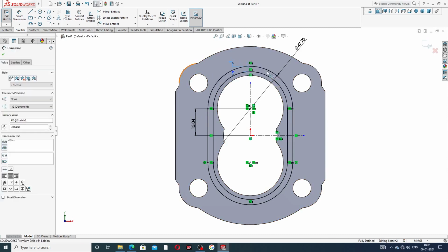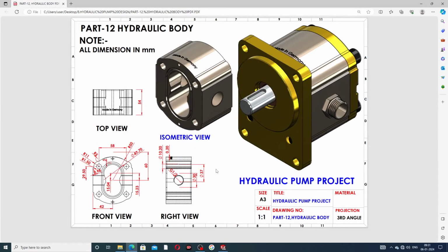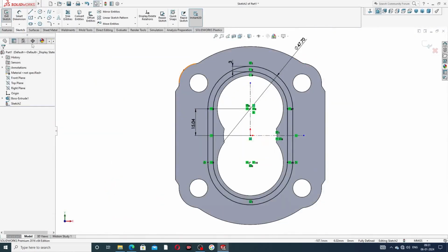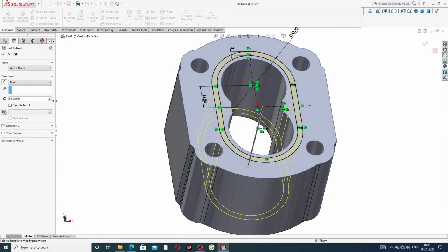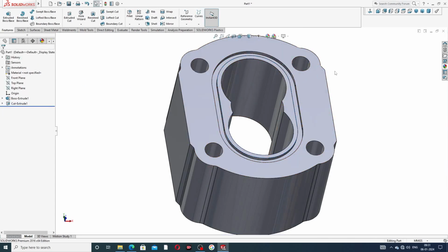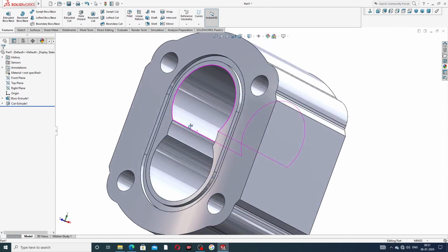This offset is used here, and the cutout is only 2 millimeter, not mentioned here, but this is a 2 millimeter cut out, using Extruded Cut. Extruded cut is only 2 millimeter because this is for a rubber belt. 2 millimeter is perfect, and click OK. This uses a washer, a rubber washer is used here, and this looks very nice.